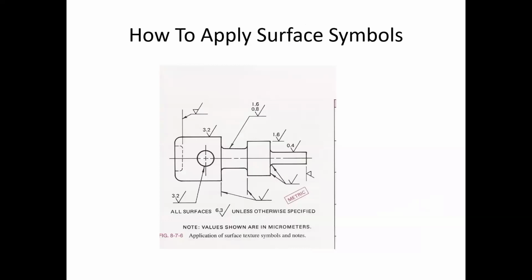All right, how do we put these check marks on our drawings? Different ways. And there's a preference in how to apply these. And this is real critical to doing well on these first drawings: trying to put these things right and really understanding where they're at is controlling what surfaces we're finishing. So you really want to have clear in your mind what that edge represents on the drawing.